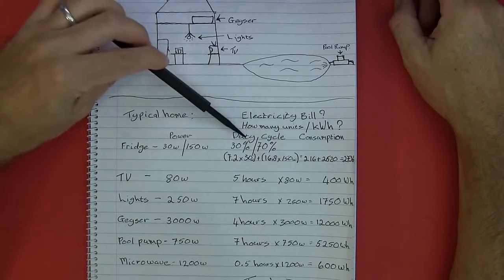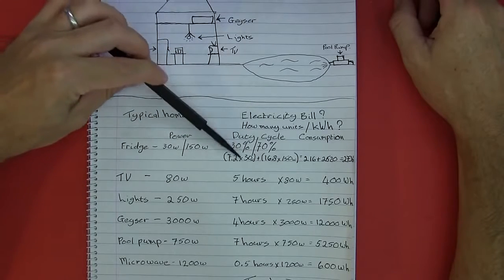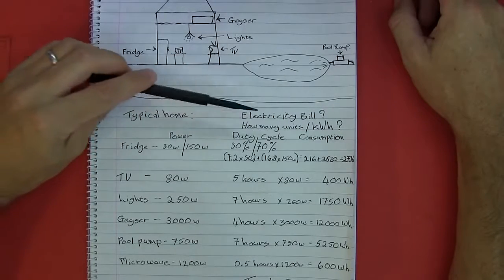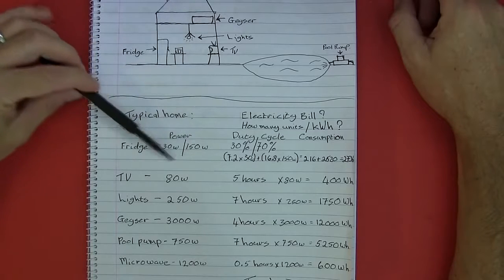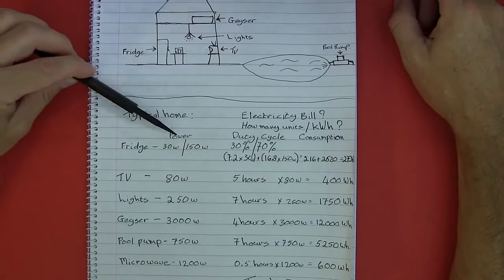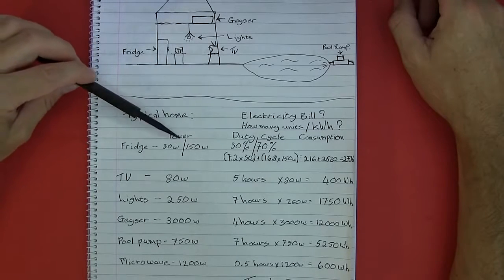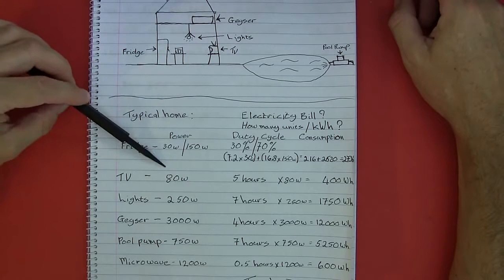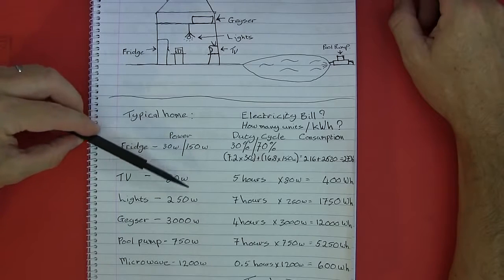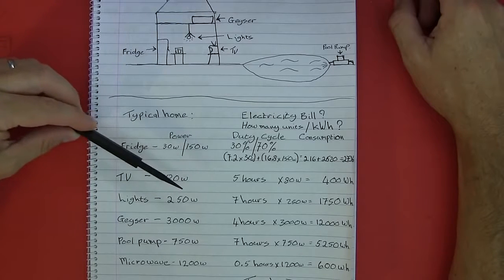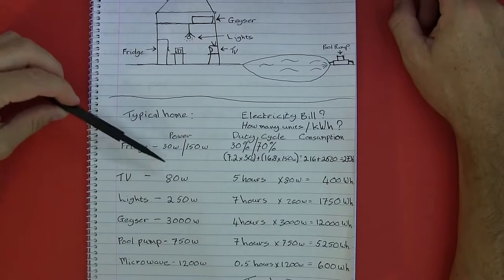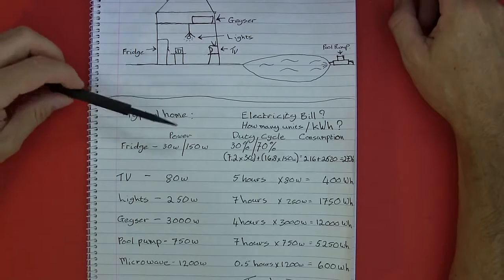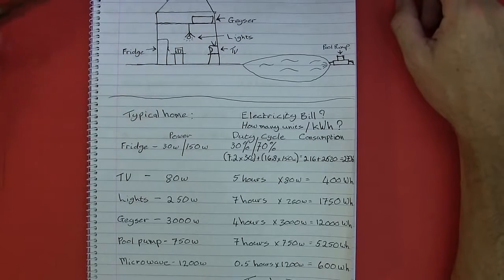So you need to understand that and multiply those figures in order to get a consumption for the day. That is why it's really important to understand these figures, and often even if you go and read them off the badges of your equipment, you won't exactly know the duty cycle, and often these power figures can be very different in reality. So that's why having measurement equipment to do these audits is very helpful, and I'll show you some of these once we've gone through these calculations.